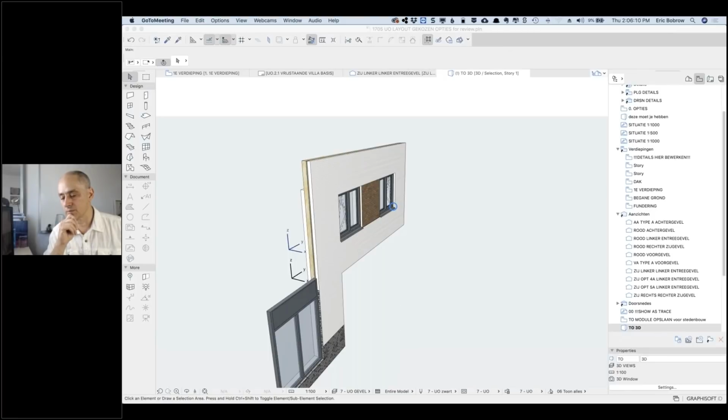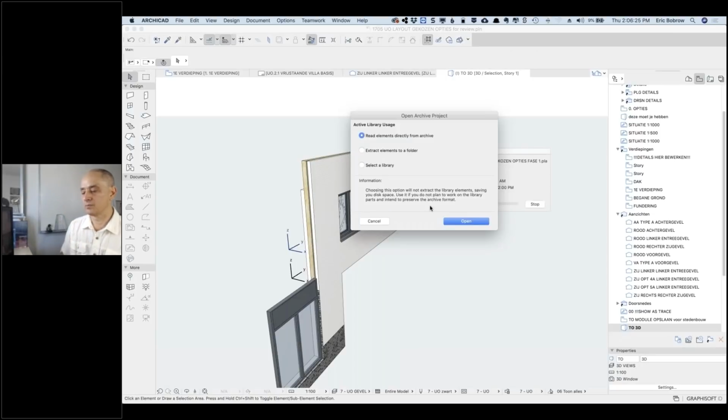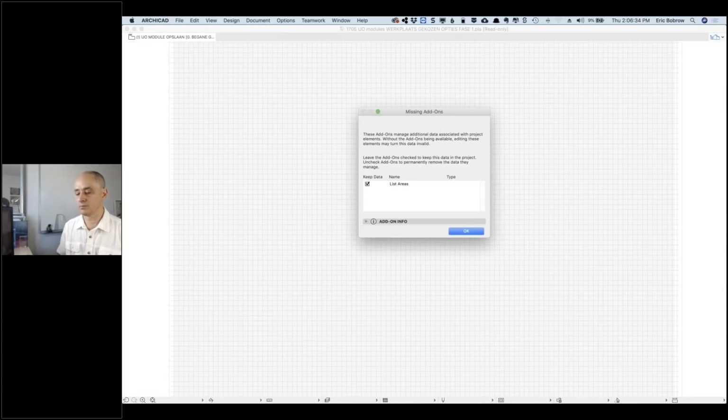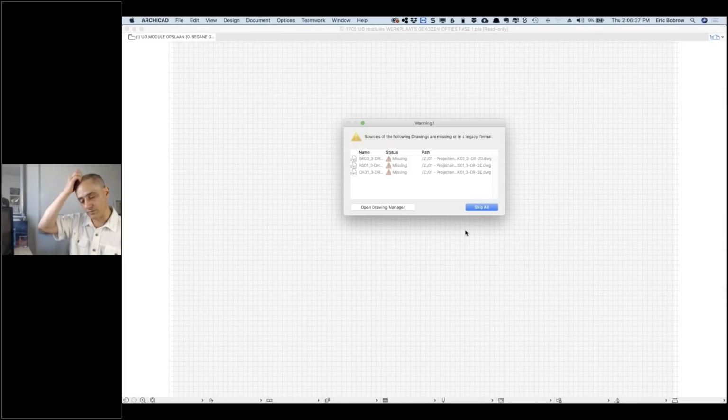And then those complex profiles were interacting with my walls, so I had to give them a little offset so they would not interact with my walls and give lines where I don't want lines to show up. And another thing is some walls were slightly tilted, and then there were modifiers preventing me from having neat, clean facades without closing lines.